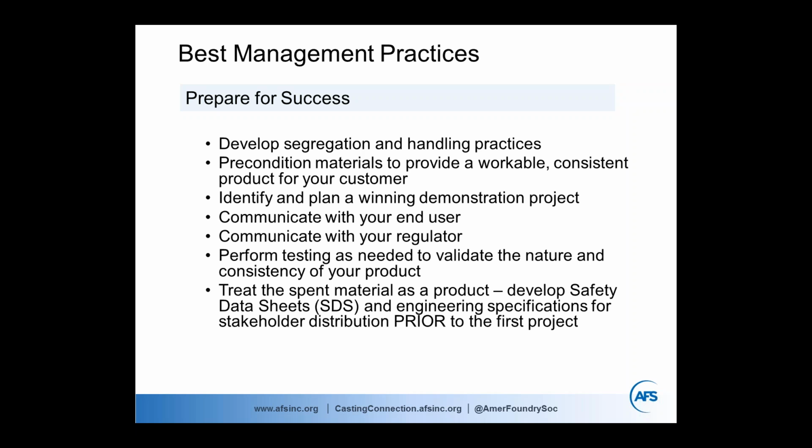It varies from state to state, but some states will say that you need to do a test once every couple of years or once every year or whatever the frequency is to basically understand the characteristics of the material. Don't be scared to do additional testing, especially when you're starting out, because having that data and understanding that consistency is a great benefit when you're communicating with your end users.